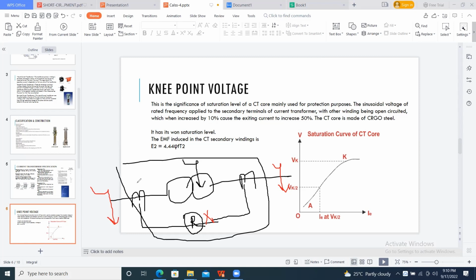So in these differential protections or restricted earth fault protections, the accuracy class and ALF of the CT, ALF like we discussed, the accuracy class like metering class CTs, or ALF for protection class CTs, may not ensure the reliability of the operation, because as I stated before, the differential protection and REF relay should not operate for faults occurring outside of the transformer.